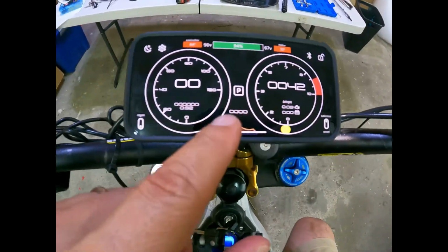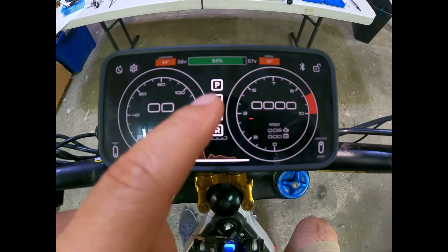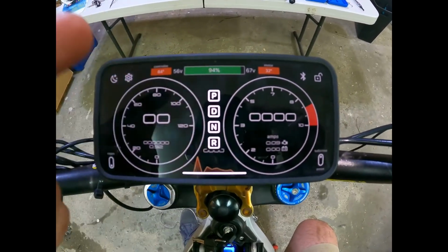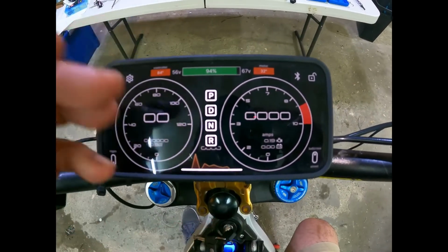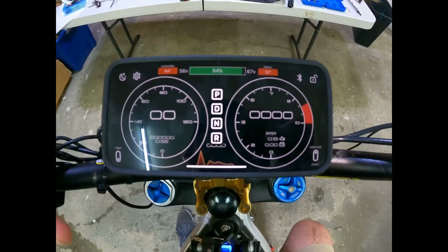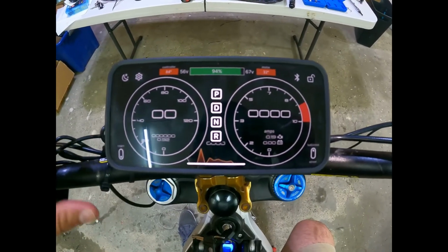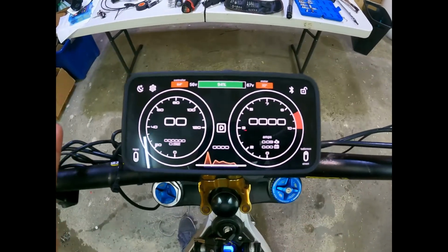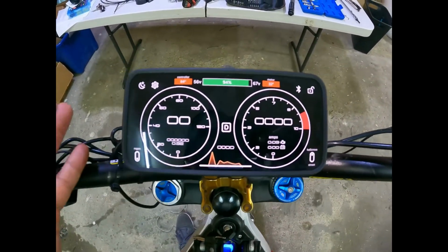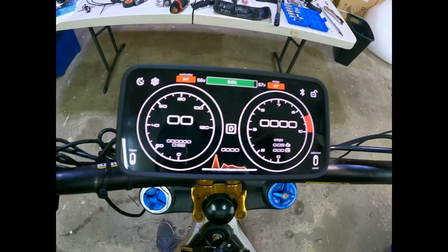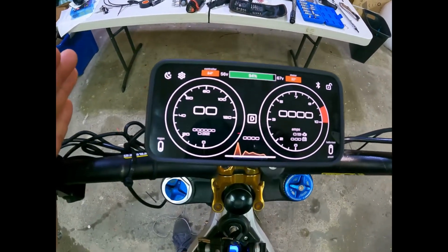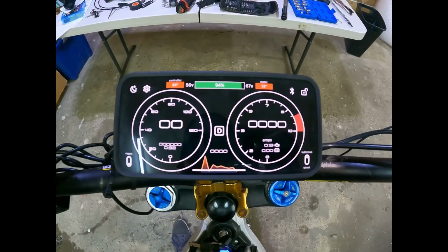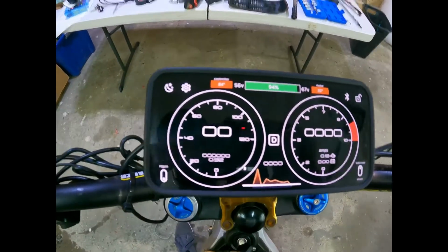Other features that we're enabling is the ability to have a park, reverse, drive, neutral. When the app is complete, when you hit park, you're basically going to have the brakes, the Regen brakes lock, and you will not be able to move the vehicle back and forth. Obviously, we're using a universal type layout because our drive system is not necessarily only for motorcycles, it's for tourist industry vehicles, delivery vehicles that we set these drive systems on. So it has to have a park, a drive, and a neutral and a reverse. But the cool thing is you'll have access to that as well.